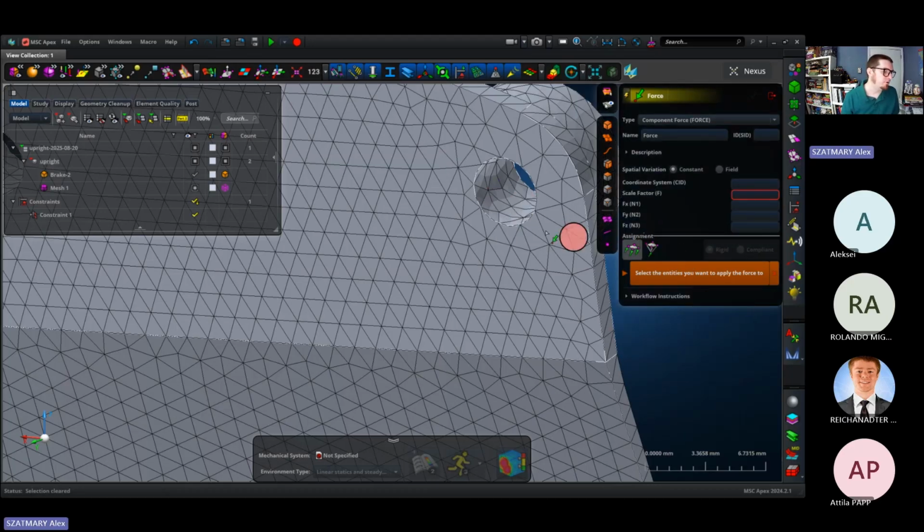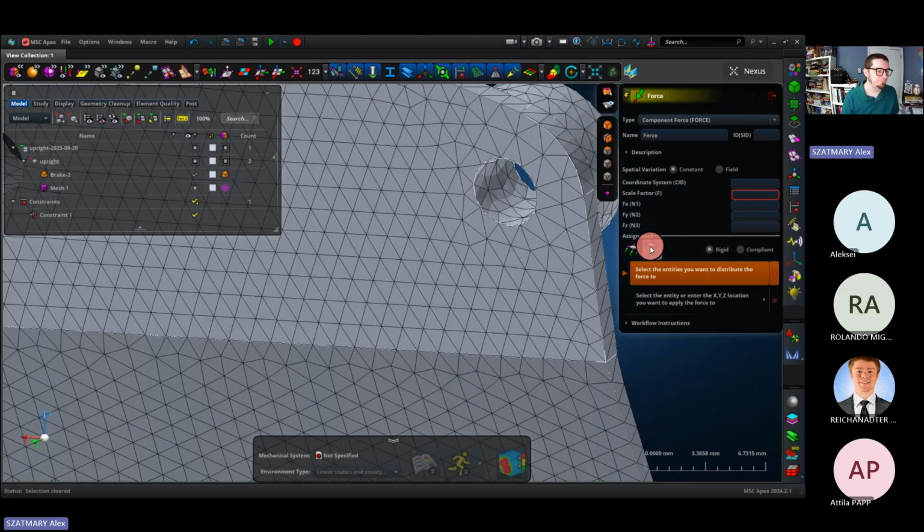A simple way to get loads applied across a surface in a reasonable way is to use discrete ties, or we could call that remote force application in this tool. And Nastran calls these RBE2 and RBE3. You can use rigid discrete ties, but those add stiffness to the model, so I will use compliant. And let me set up the numbers for the force that I'll apply. We'll use a scale factor of 1 unless we have a reason to do otherwise, and I'll enter the vector components that I'd indicated on that slide. -8, -97 in the Y, and -236 in the Z direction.